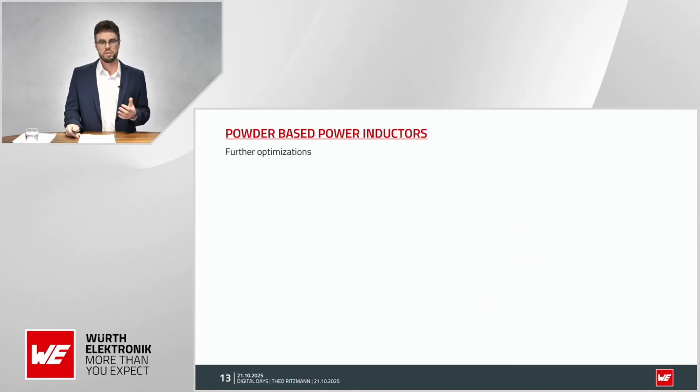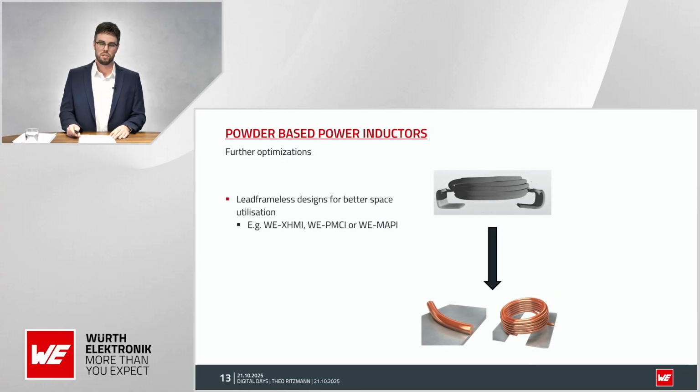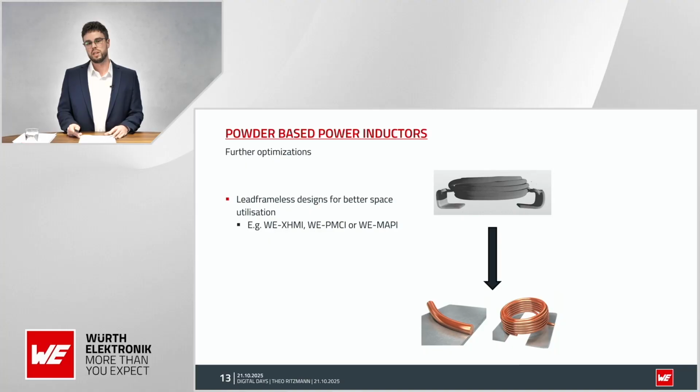Then, next to the materials, also we had some further optimizations, especially when it came to the molded inductors. So one change was, for example, the lead frames. Lead frame was always kind of occupying some space inside of the inductor, and therefore lead frameless designs became more and more popular, like our WE-XHMI, WE-PMCI, or WE-MAPI series.